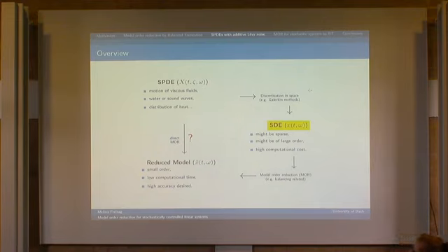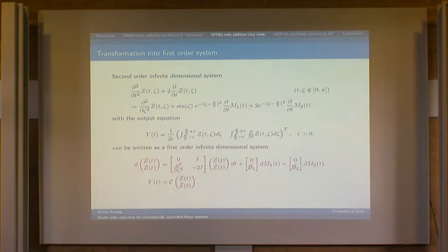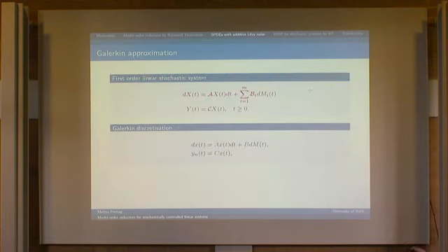Okay. So you've got a stochastic differential equation. How do I get to the stochastic differential equation? I don't want to go into too much detail, but you have a second order ODE, you replace it by a first order ODE with a larger dimension, and then you discretize it and you end up with a system like that, a system that I talked about earlier. It's almost the same as for the deterministic system, but you have a stochastic input here. And you want to see how this is propagated through the system and what the output looks like.